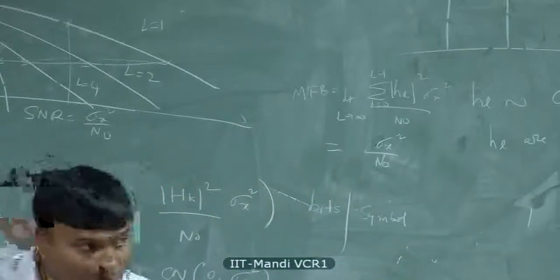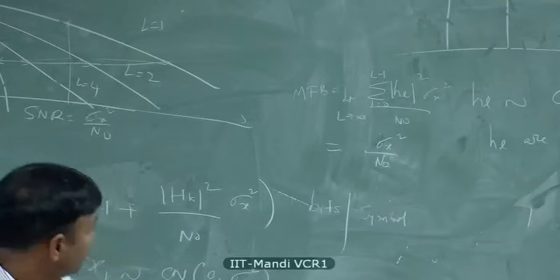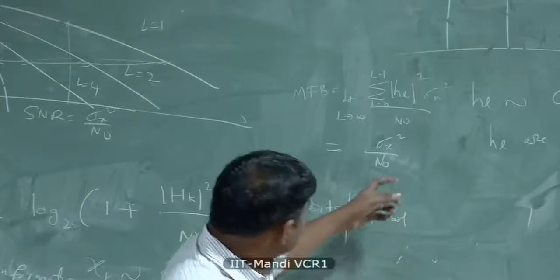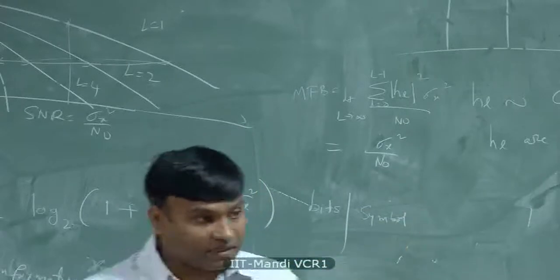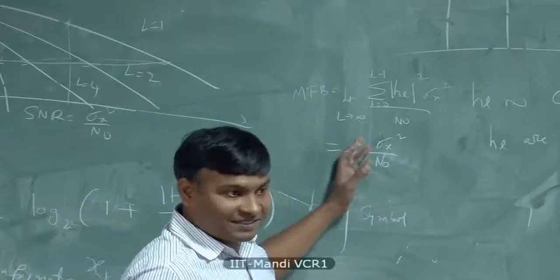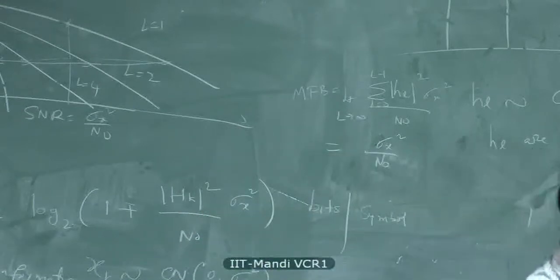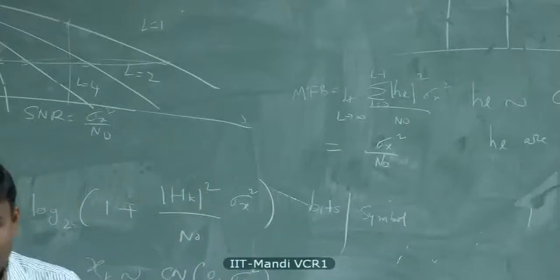In a broadband channel with plenty of multipath delay spread, if you design the encoder and decoder properly, this is the limit for your receiver. And you may say, oh, well, can you have an infinite number of taps? Well, a number as close as 5 or 10 gives you an effect close to infinity. You know that, with the central limit theorem, after you sum up 5 or 6 random variables, the central limit theorem effect kicks in. So if you have 5 or 6 independent fading taps with approximately equal average power, you will get this effect.